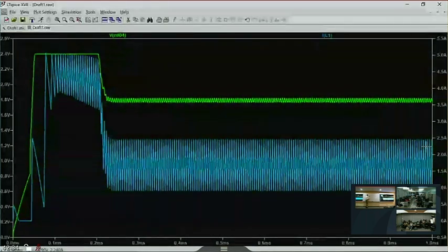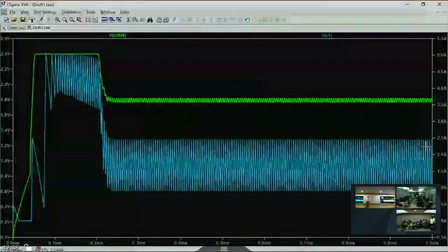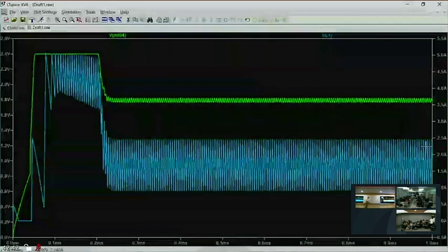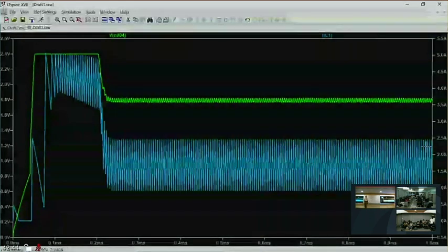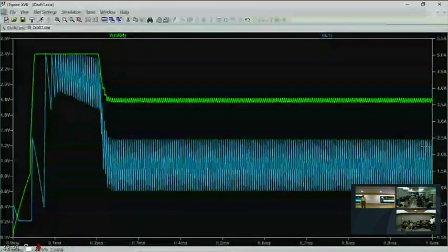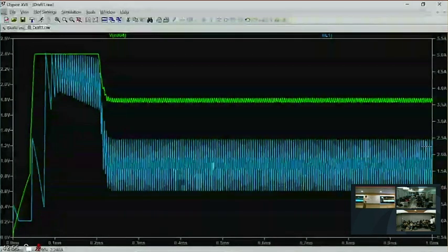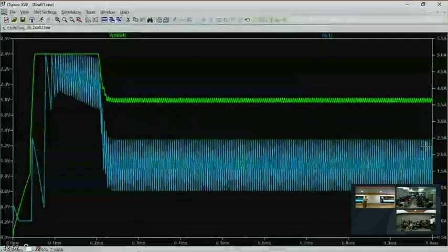So we'll take some of this signal and add it to the inductor current. Where the current ramps up, we'll add a ramp to it. And if we reset according to that quantity, you eliminate the ambiguity between peak current and average current on a cycle-by-cycle basis, and you get rid of the subharmonic oscillation. That's what slope compensation is. That's why it's done. And if you look at these two waveforms very carefully, you can see that that is exactly what the controller is doing.